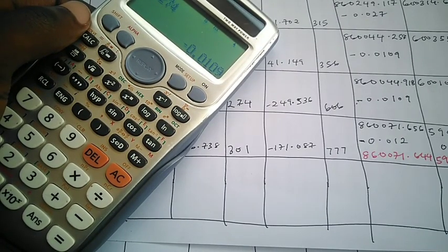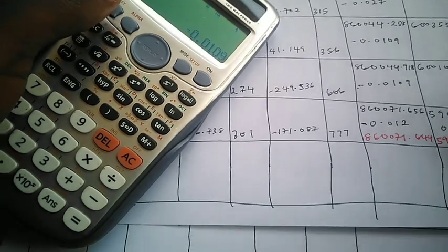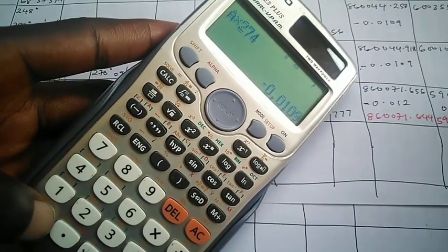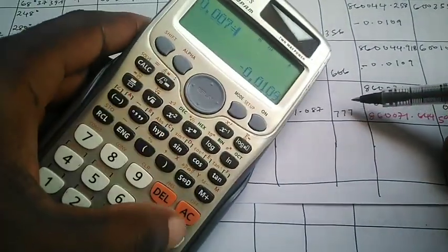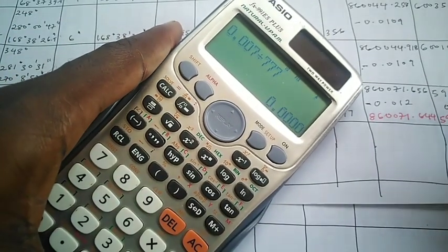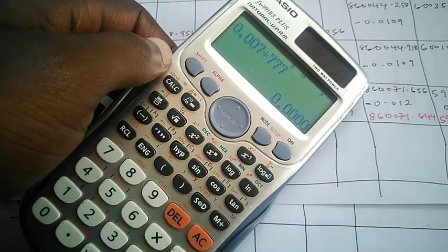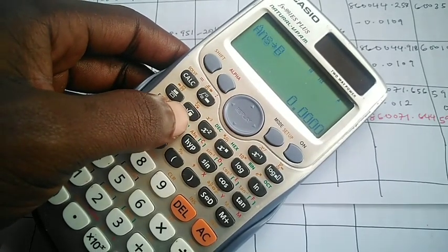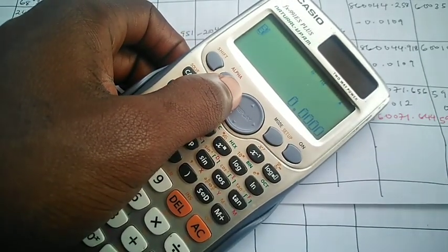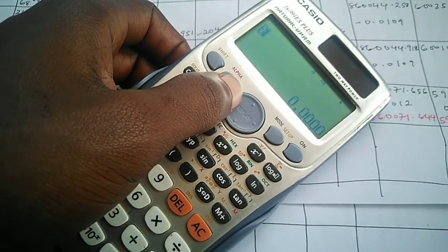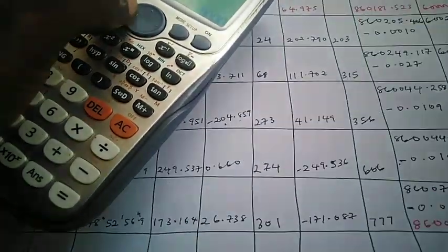So we are going to do the same thing for our eastern. In this case, we are saving it on the letter B for the eastern. The error for eastern is what? 0.007. So we have 0.007 divided by our last arithmetic sum here, which is 777. We have this quotient here. Since the values are still small, you still see them as 0.00. So you know what's happening now, as I've explained earlier. Let's put it on alphabet B. So recall alphabet B, and you still get your 0.000 because the values are very small, maybe to fifths or whatever decimal there. Now let's multiply it by the arithmetic sum of the first station.